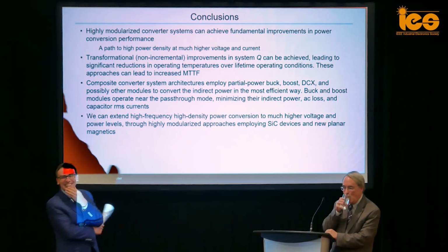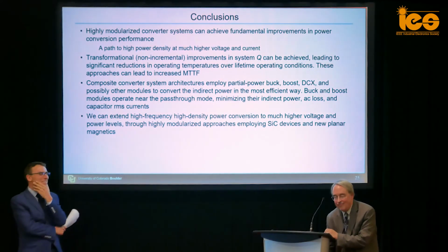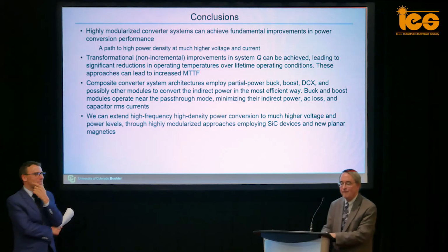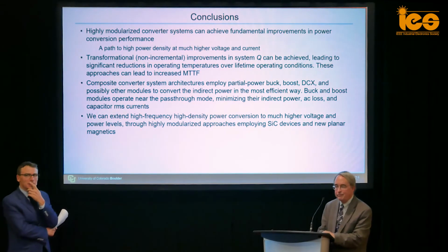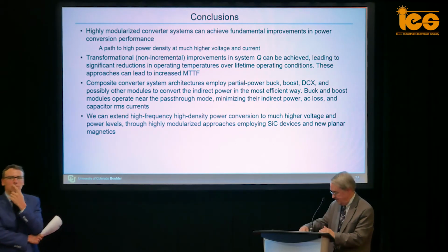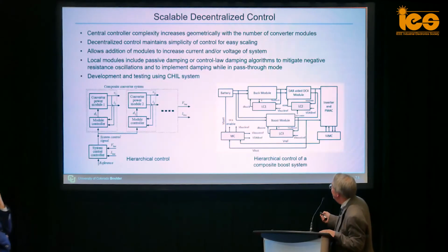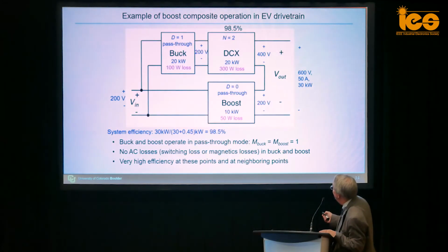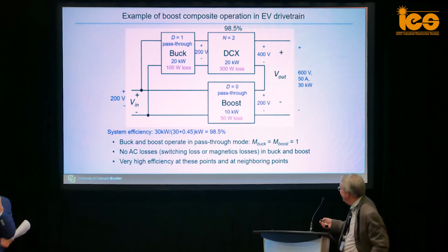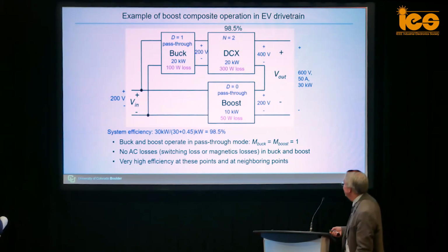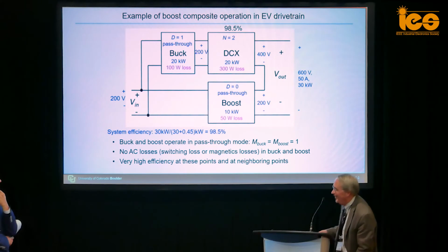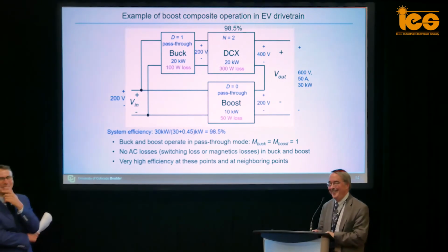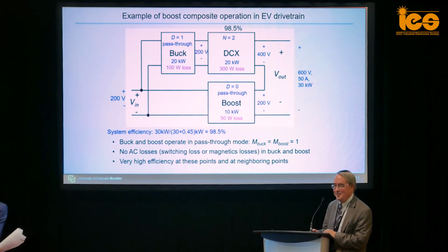I like the idea of having the 3 boxes to deliver the same output power. But how did you come to optimize that the boost converter is working at zero duty cycle? So it's almost pre-regulated, the 3 bucks, like for example here. So you have the D0 here for delivering 10 kilowatt with 50 watt. I never worked with a boost with D equal 0, but you must have D equal epsilon to throw the power. But how did you optimize that you are pushing in the buck converter 20 kilowatt and in the boost 10 kilowatt?